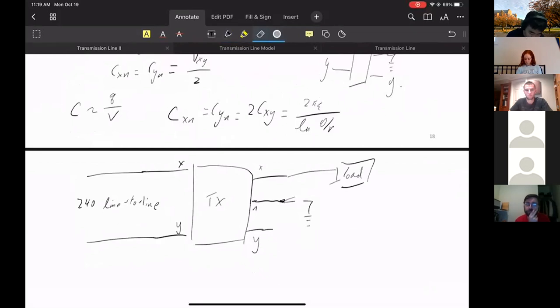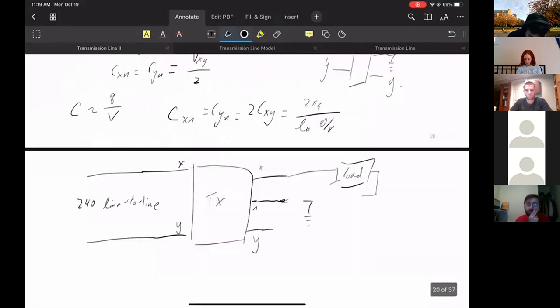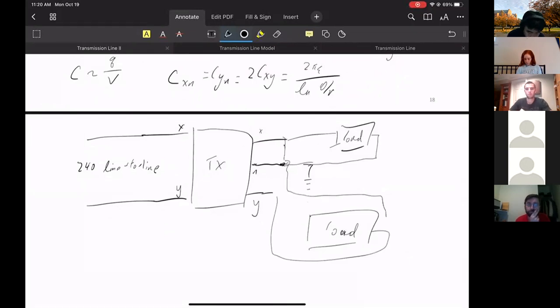Let's draw a little bit better. So your load is 120. The way it connects is something like this. This is your load connection. If you have a load that's 240, so you have a kitchen or a stove that's 240, then you connect it this way, in your 240 connection. So this is sort of the wiring that goes down in your home.